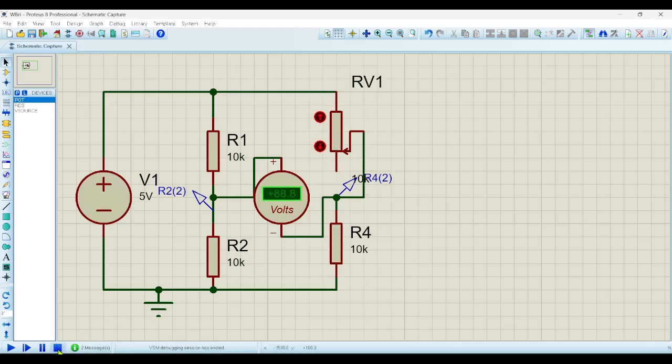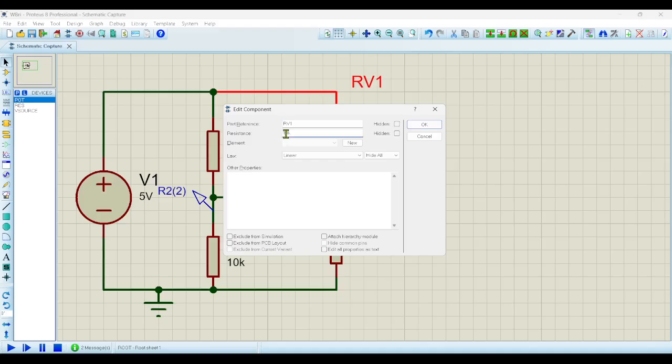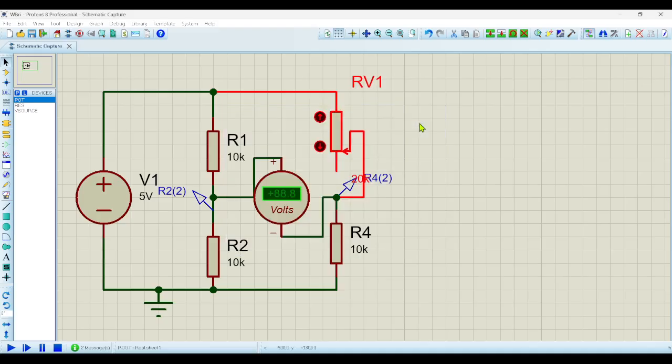Let me change the value of the potentiometer once again. Let me put now a 20K potentiometer. If I check right now, the voltage is not 0. I will move its value until I get a 0. Right now, I have a 0 because I am at half of the 20K, right? So I have here 10K, and that's the same as this. So I have the same relation. So now, depending on the value here, I can get which value I have there. So that's a really useful result, right?